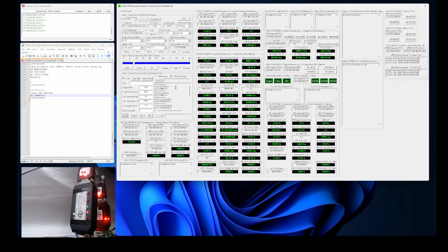For example, the first one: for each line, when you have a semicolon before it, it's a comment. Now you can turn off the CAN bus. Use AT command space CAN bus equals 0. To turn it on, you can use AT space CAN bus equals 1.